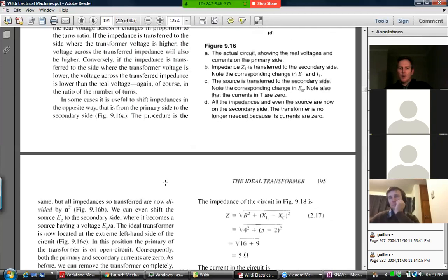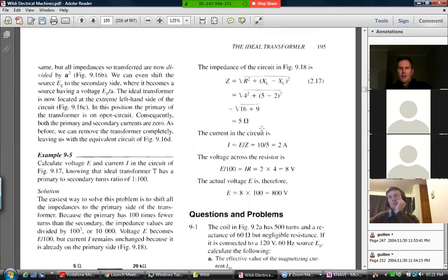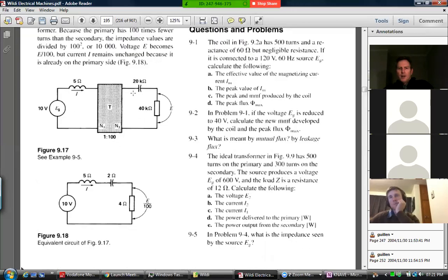Okay, so where does that leave us? It leaves you having a little look through that one yourself. All of these things, there'll be a similar procedure. Take each impedance and move it. So that one moves, it stays a capacitor. This one stays a resistor. Once they've moved, you can now add them together. We can add that resistor and get a combined R. We can group that with this X, XC for capacitor.